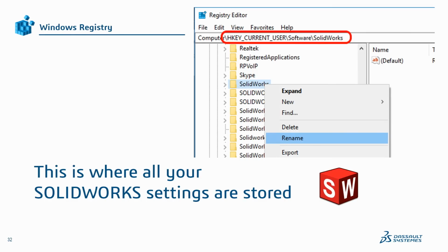You could try this. I mean, yeah, you could try this. The only reason I'm hesitating to answer is because in my experience, let's say I've got 4 versions of SolidWorks installed, which I have currently. I've always been totally fine launching the newest one first and working backwards. So step 1, I'll rename my registry. Step 2, I'll launch 2020 and then work my way backwards. And the new ones never look back at the old ones.